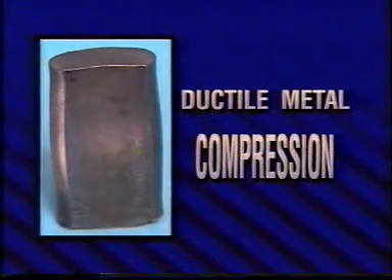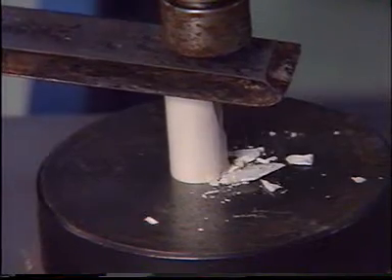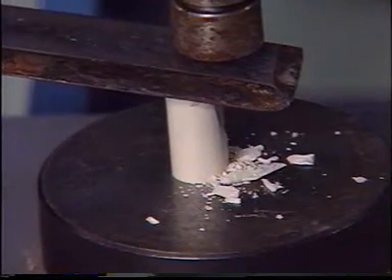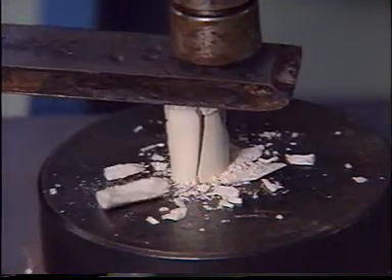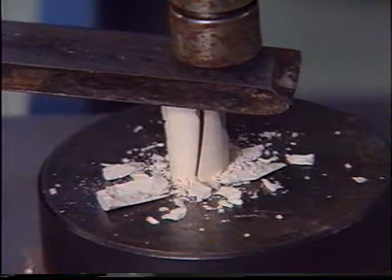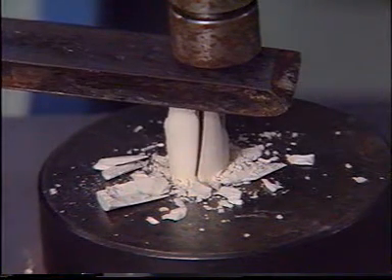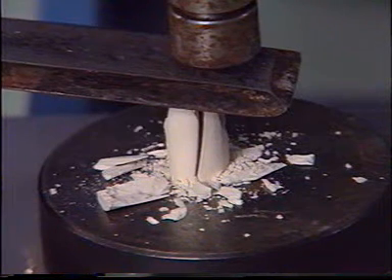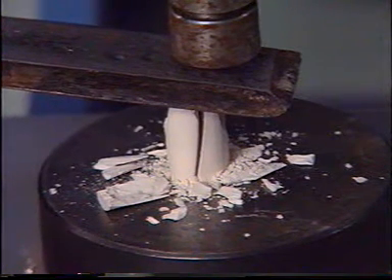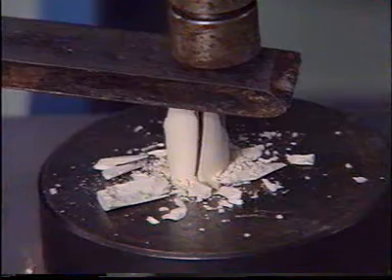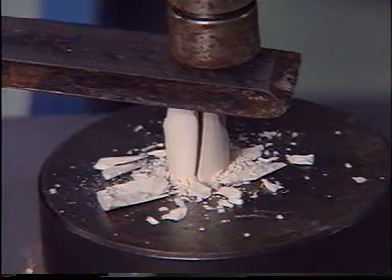Ductile metals in pure compression do not fracture. A truly ductile metal will simply bulge laterally as it becomes shorter. A brittle metal in pure compression will, as always, fracture perpendicular to the maximum tensile stress component. Brittle materials such as glass, chalk, rock, and very brittle metals split or shatter longitudinally in many slivers when loaded in compression. The increase in diameter and circumference with the increase in circumferential and radial tensile stress components causes the brittle material to shatter longitudinally.